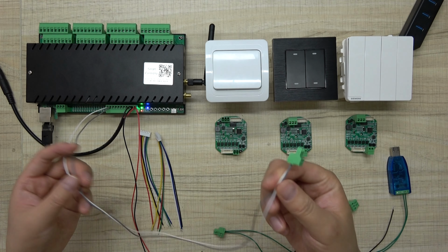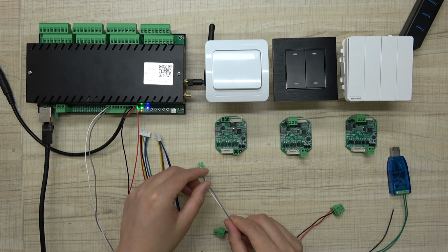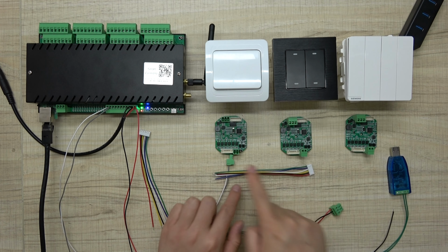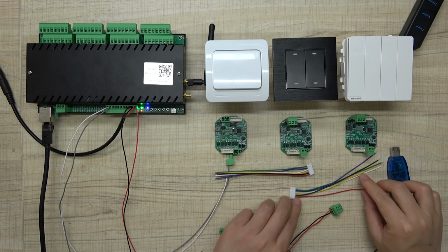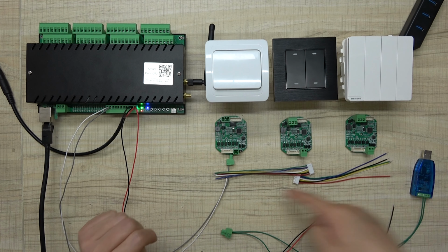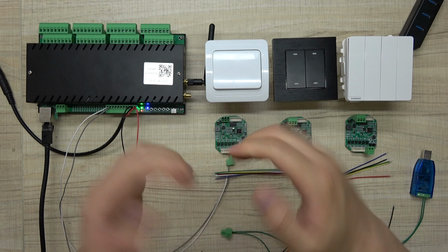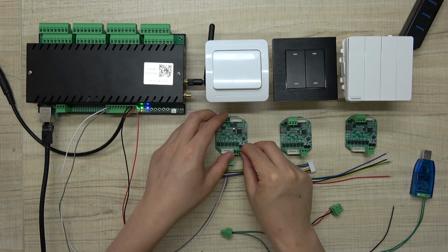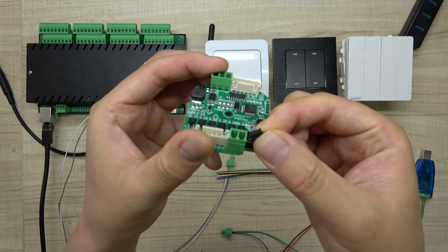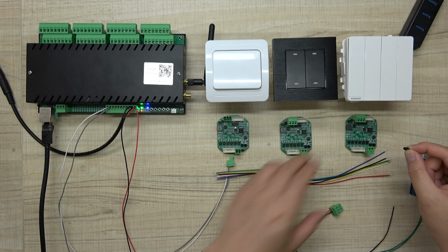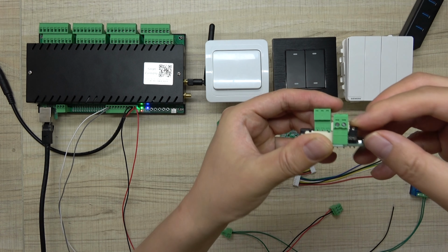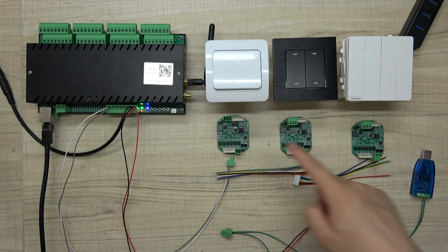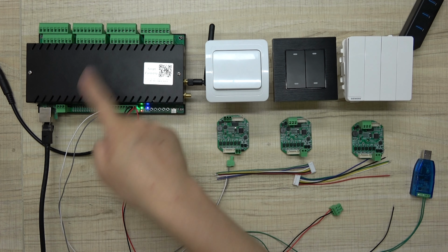So you can connect your RS485 interface cable to the first one here, the second connects to this board, and the third connects to this board. So it is one by one, hand by hand: this one to this one to this one. But this time you need to change the jumper. Change the jumper to the last one. So for the last one, you need to enable this jumper here. So these 3 switch panels will work together in one relay controller system.